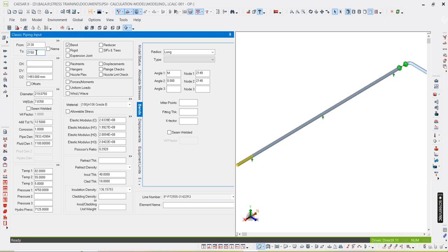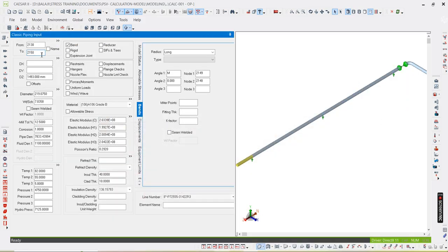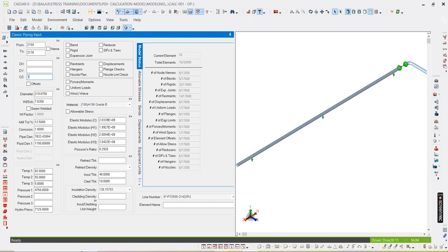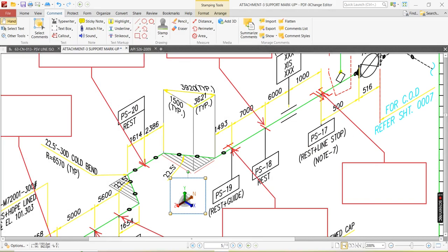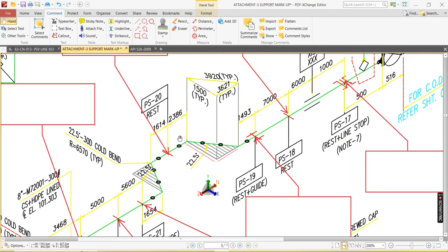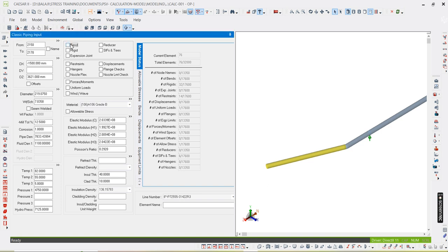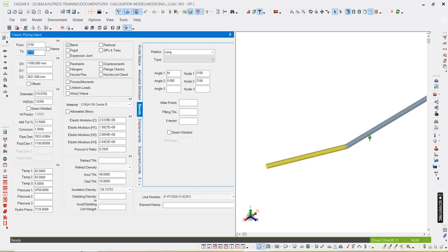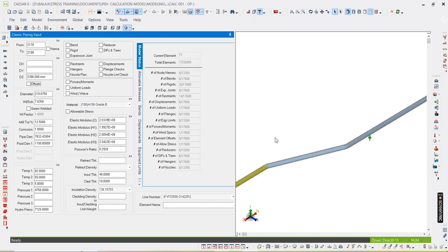We have defined the bend. After that, 3621, 1500. 3621 in Z direction and minus 1500 in X direction. You see, you got the pipe, okay, in different direction. So again, what happened? The line is traveling in Z direction. Bend is there, so you have to define bend here, and then line is traveling in Z direction, 2386, plus X plus Z direction, 2386.